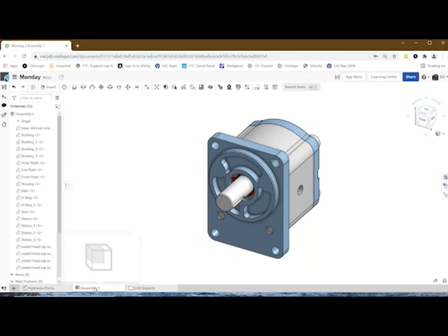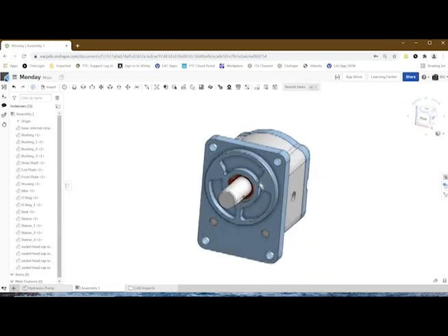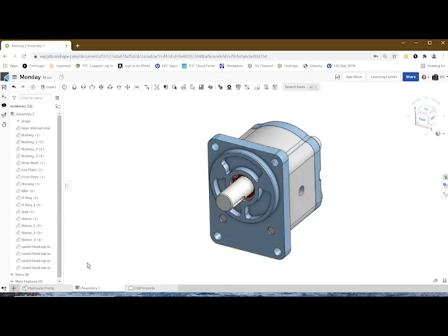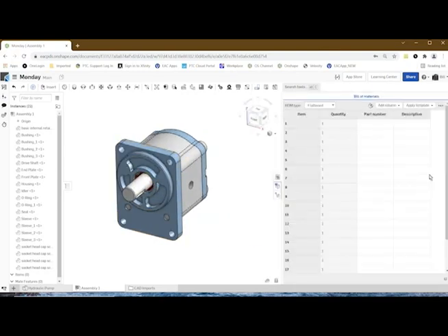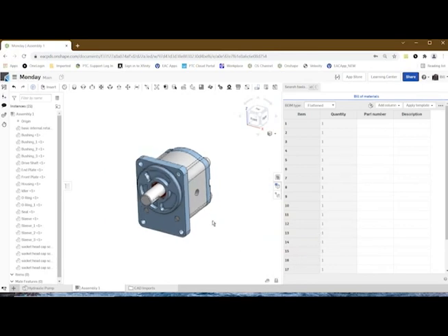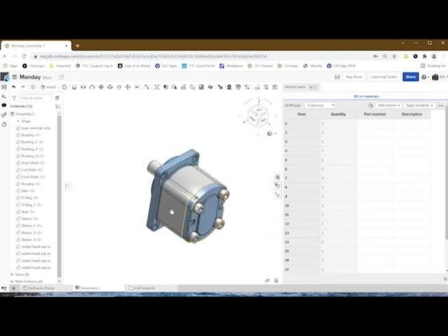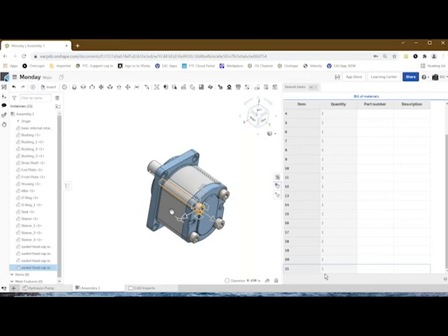So now we have an assembly, you can see from the tab down here, and we can take a look at it. Now, because the assembly and the PartStudio are the same, the PartStudio had the 4 bolts that were brought in. If we look at the bill of material for this, we can go and take a look at it, and here are all the bolts in the back. And you notice that if I pick one bolt, it's down there. If I pick another one, it's right there. So all 4 bolts are independently listed, right? So that's not a good thing.